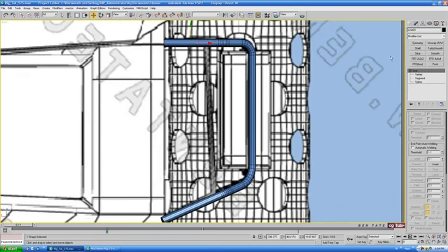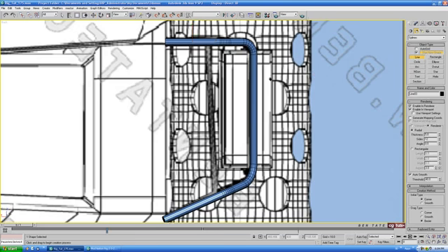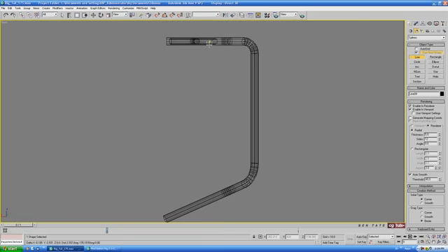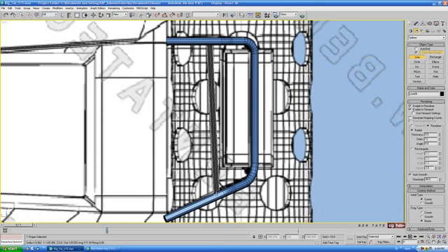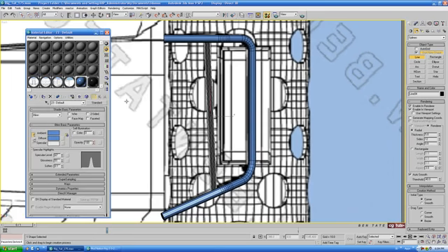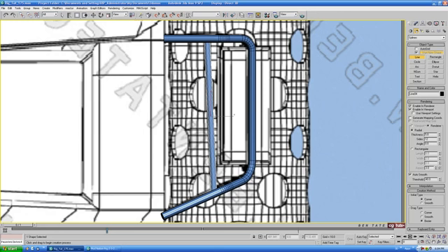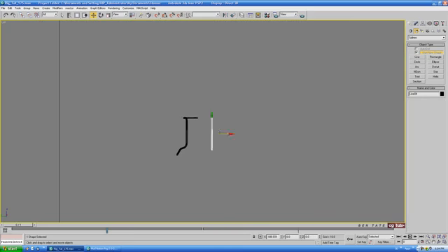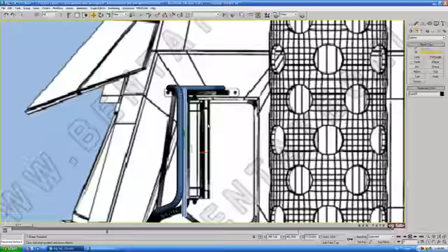And it'll probably be the easiest for us to see here, obviously, in the back view. So let's grab another line, and we'll do the exact same here. Start here in the center of the spline up top there, and just bring it all the way down to the bottom. Click, then right click to end. Let's throw our blue material on there. We'll leave the thickness at 5 for this one, and we'll just move this over in the left view, and we'll try to line it up.